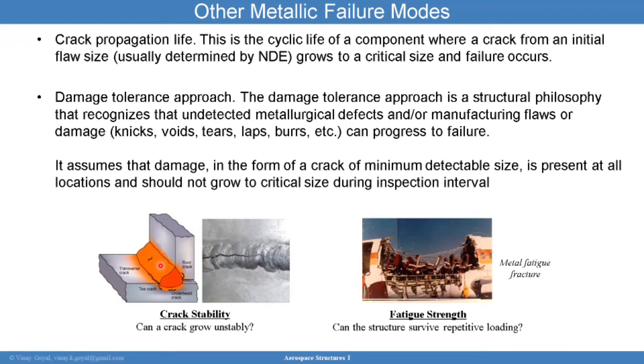If that's the lowest I can ever detect, then sometimes what is done is that you do a crack growth analysis starting with that 40 mil flaw. Even though your structure doesn't have that flaw, it's conservative to assume that if I have an inspection technique that can inspect for that, then I do an analysis assuming that every part has a flaw of that amount.